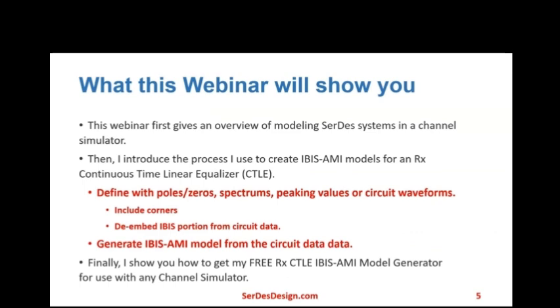What this webinar will show you. This webinar first gives an overview of modeling SerDes systems in a channel simulator. Then I introduce the process I use to create IBIS-AMI models for receiver CTLEs. Define the CTLE with poles and zeros, or with spectrums, or with peaking values, or with circuit waveforms. Include the ability to de-embed the IBIS portion from the data collected to derive the AMI portion, and generate an independent standalone IBIS-AMI model from the data. Finally, I show you how you can get a copy of my free receiver CTLE model generator for use with any channel simulator.